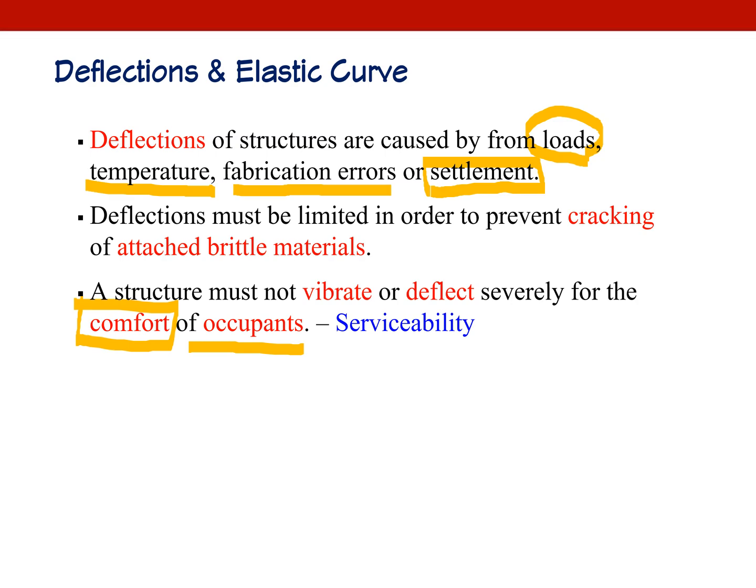vibrating element. But those are not really strength issues, so we are going to call it serviceability. The opposite concept of serviceability is the strength issue. So we have two limit states, the serviceability limit state and the strength limit state. The serviceability limit state is not related to collapse of a building, but anyway, occupants may not like it.